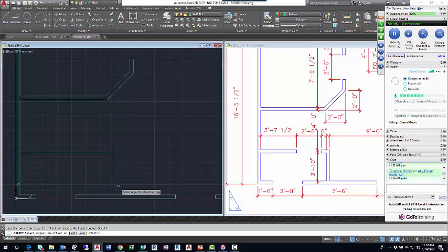That's the top line of the top of the wall of this. This is a water closet, like a toilet room. So I did 4 foot offset, and then all the walls are 3.5. So I'll go offset 3.5, enter. Left click that new line I made, move down and left click.